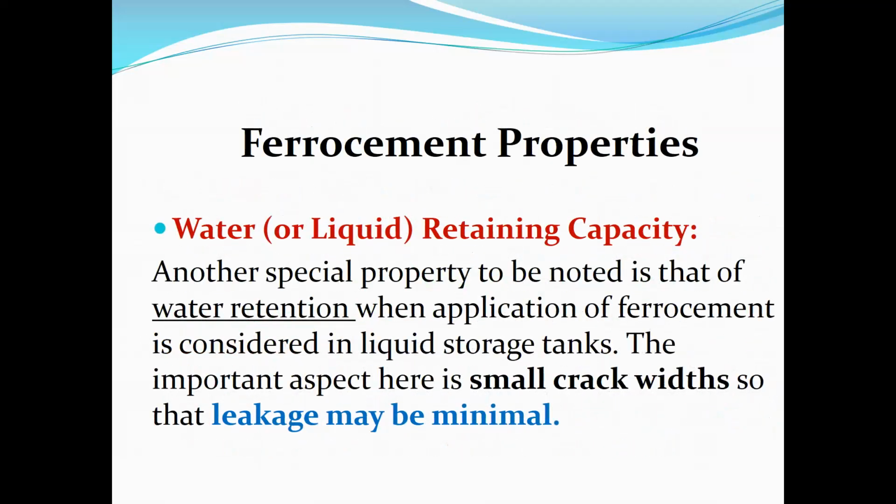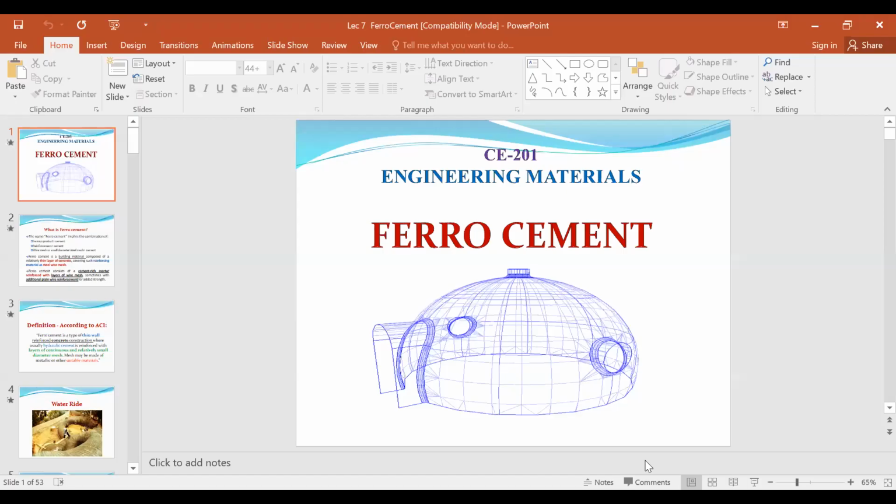Water retaining capacity is good. It is a special property of ferrocement that it can retain water, at least in the case of liquid storage tanks. In the picture we saw, ferrocement structure is preferable to some extent for liquid storage tanks, because the cracks that develop will be small crack widths, so the leakage will be very minimal. That's all about ferrocement structures.